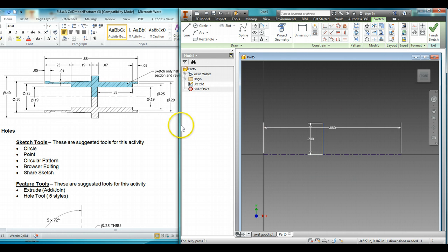I'm going to locate this vertical feature the proper distance away. When I follow that feature up, it says 0.19 and 0.25 there. It doesn't actually give me an actual length measurement. Again, I'm going to let Autodesk Inventor do the math for me. I'm going to delete some of these measurements just to keep it fairly clean so you can see what I'm doing.